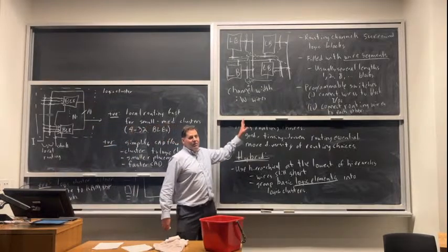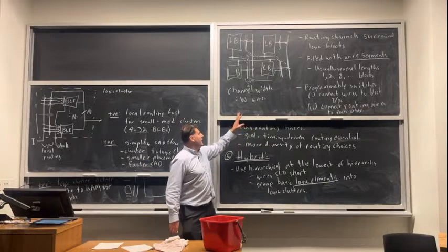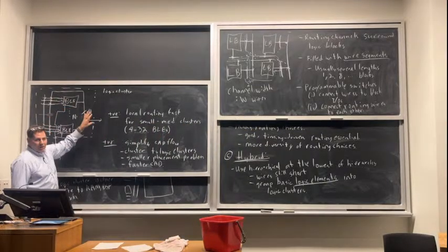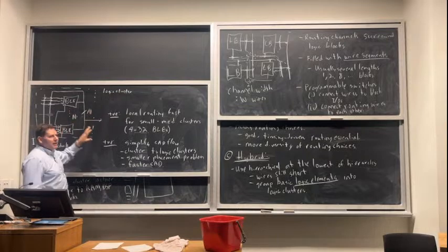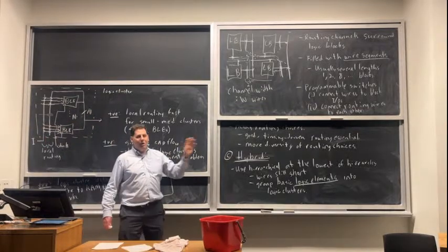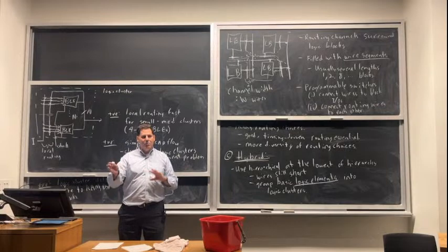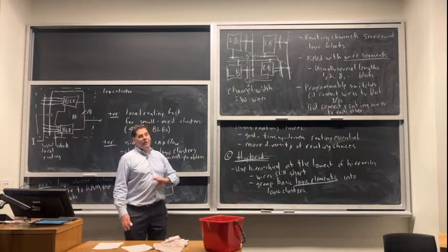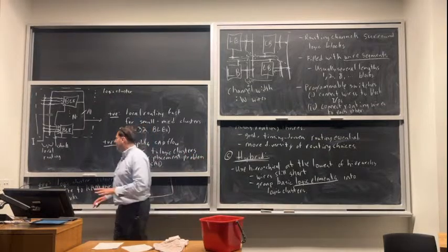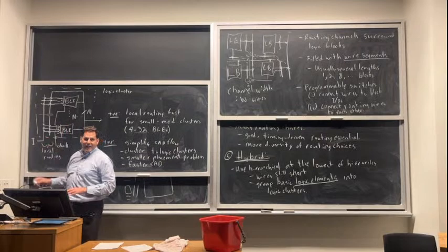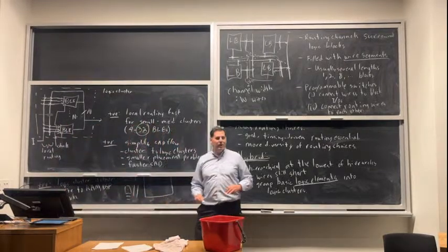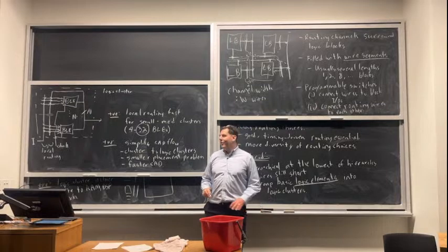Xilinx basically went the other way. They've gone to this kind of more complicated logic block, but their local routing was more complicated. Okay, their local routing had a more complicated set of wires, and it was easier for there to be blockages. And then in their latest generation Versal, they basically said, we love local routing, and they've made their logic cluster 32, actually. They made the biggest logic cluster of anybody. So it's kind of interesting.